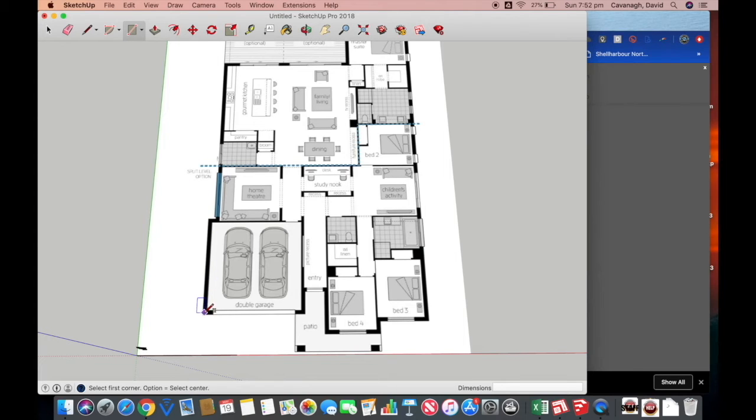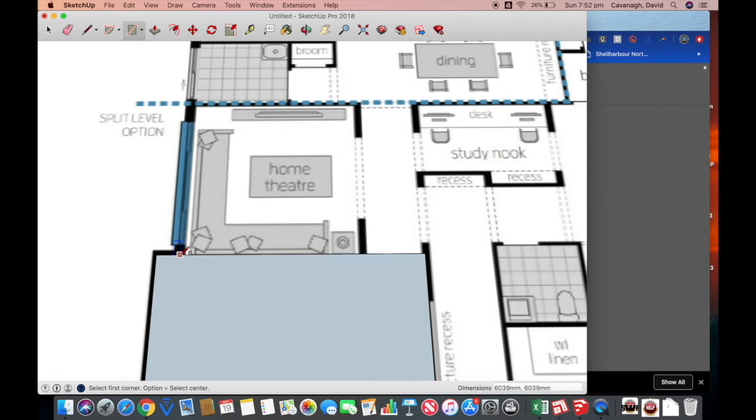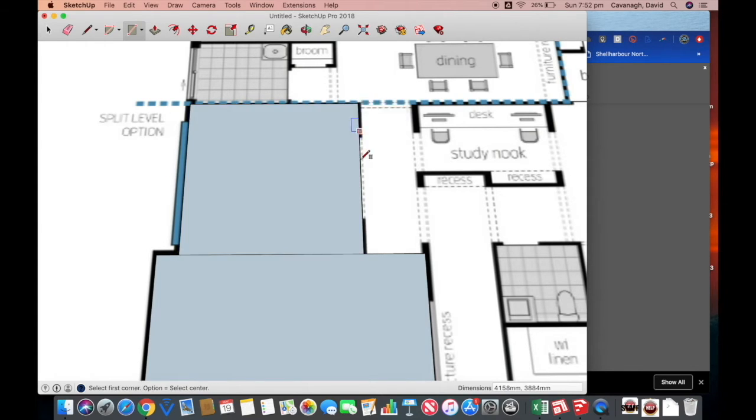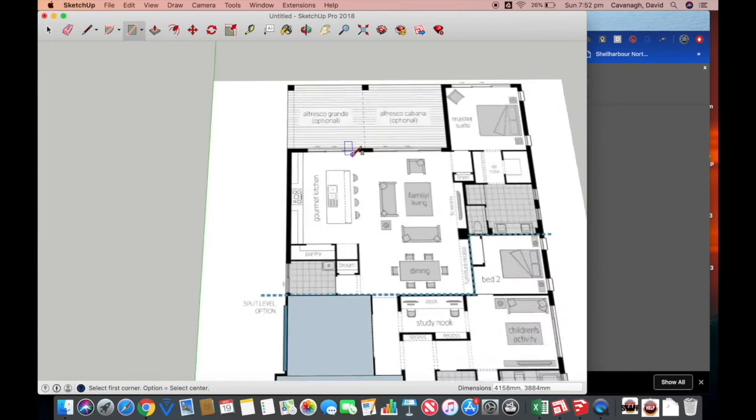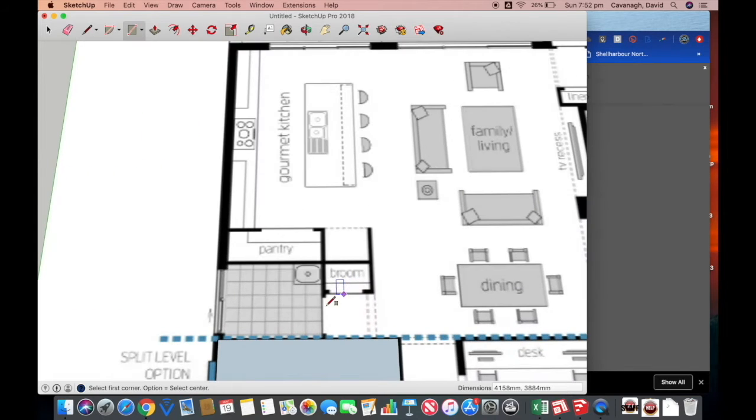Now what we're going to do here is pick up the rectangle tool and draw squares over our rooms. It's important that once you draw a second square and then on, you draw from a point that's already existing on the house. So I'm starting from that left bottom point of that square and dragging up from there. Don't start from in the white zone and drag it back to a room. Always start from an existing point.